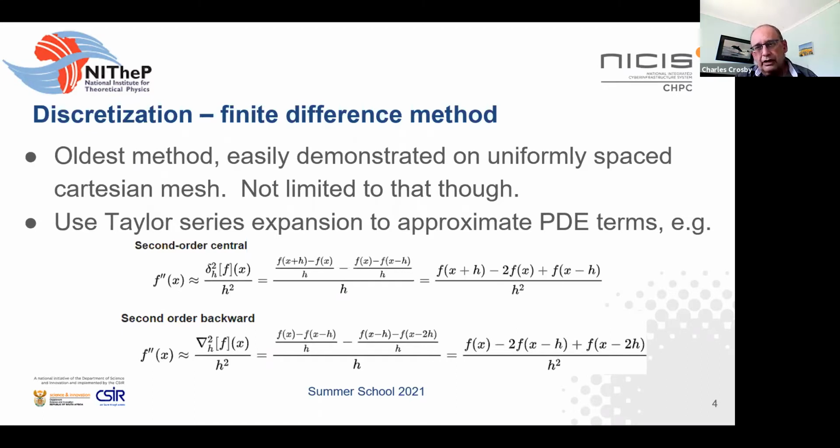So you need to go to higher order upwind biased schemes to get you both stability, but also a form of accuracy. And this is, of course, where a finite difference method has got a great advantage, because you can just do more terms from your Taylor series. You can just go to a higher order in your Taylor series expansion, because you know where the upstream grid points are and what their values are.